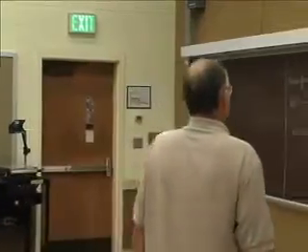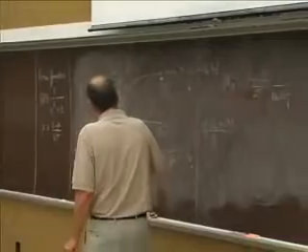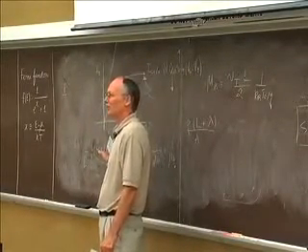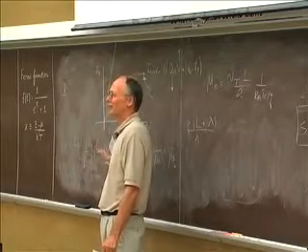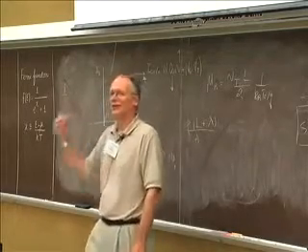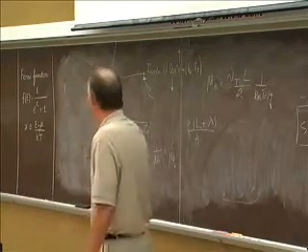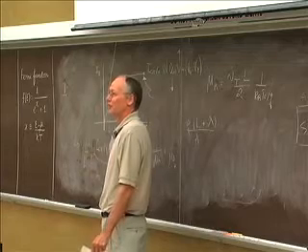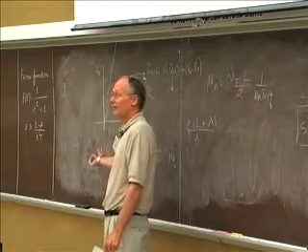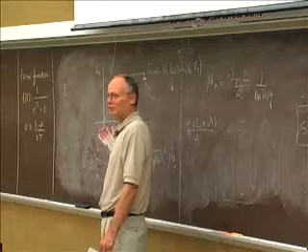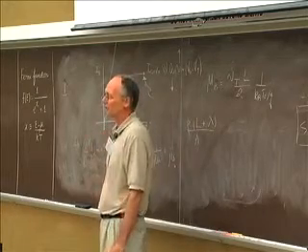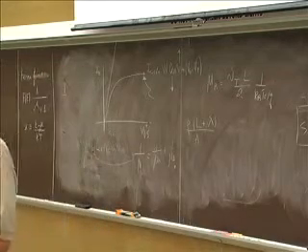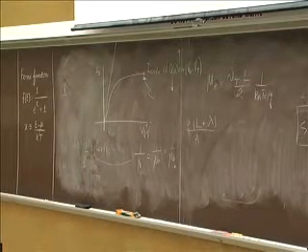These days, one of the other reasons that III-Vs aren't quite as attractive an alternative as they were initially is that silicon never stays still, right? These guys are always doing clever things. There's been a lot done in recent years on strain engineering, straining silicon effectively to lighten the effective mass and get a lot of these benefits, which makes it even harder for anything to compete against silicon. But as I said, you work the numbers, it looks like there's an advantage there, but it's got to be done in a well-designed device.